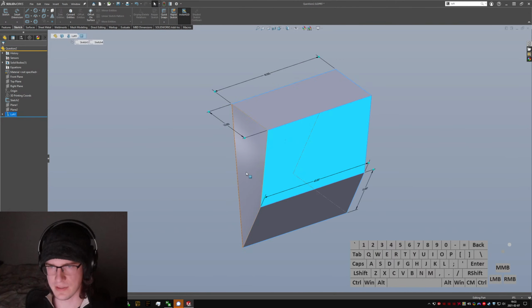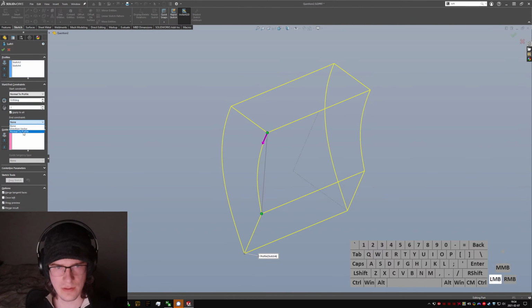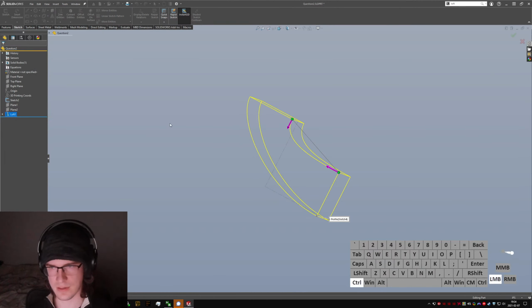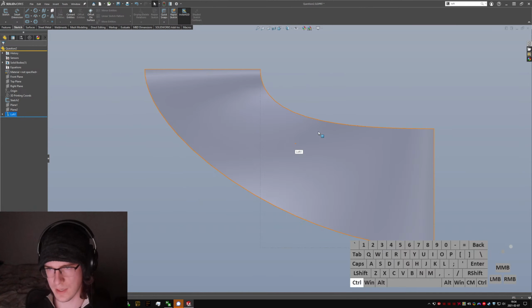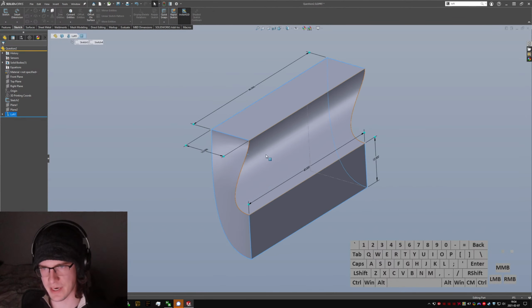So, we're going to fix that by giving us a normal to profile constraint. That is kind of messed up on this one, so if I reduce the strength on the guy up here, it'll come in a little more clean. Yeah, that looks about right. This probably isn't perfect. I think what I want to do is maybe generate an ellipsoidal surface so that this is really clean. But if all you wanted was a duct between these two, this would technically work. But I'm not really a huge fan of how it doesn't seem to be kind of a constant area thing,